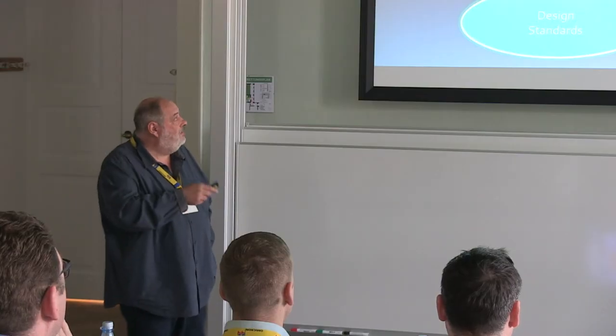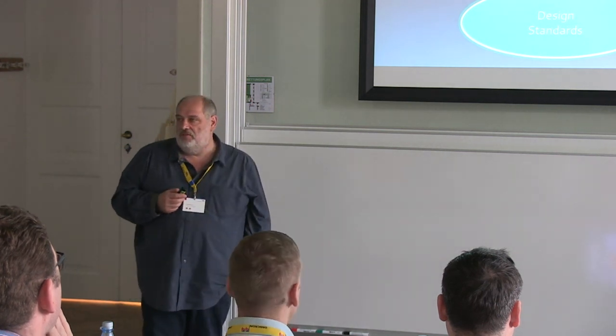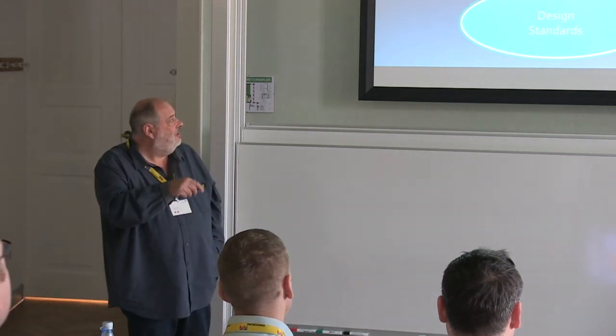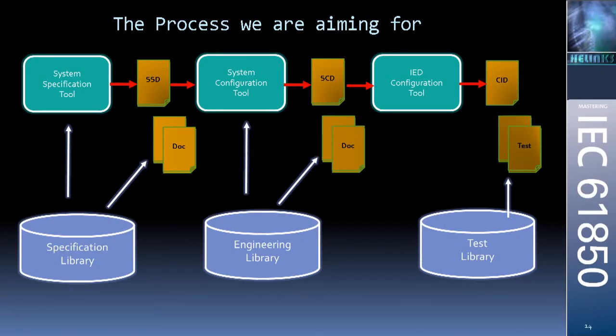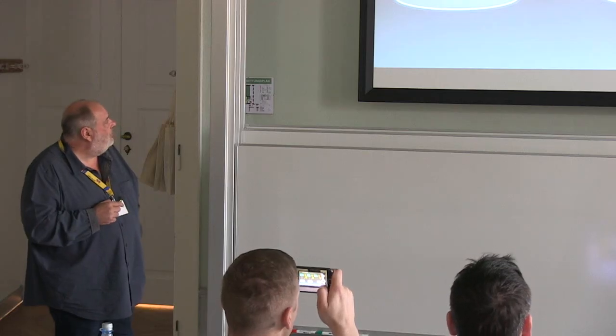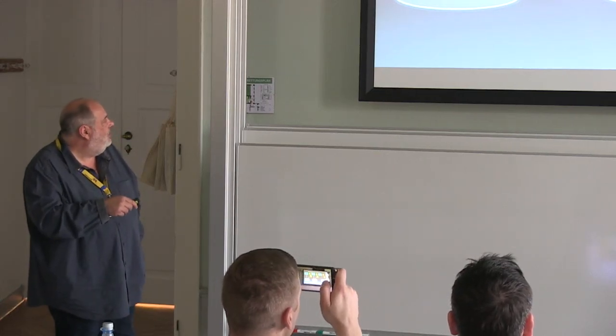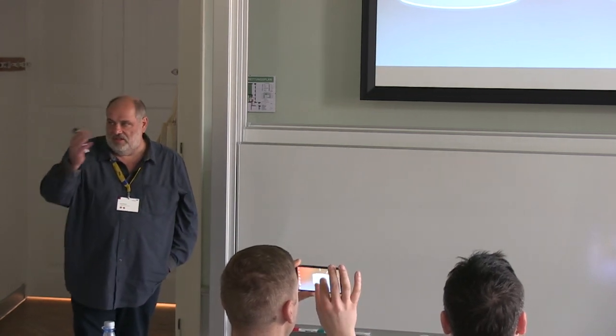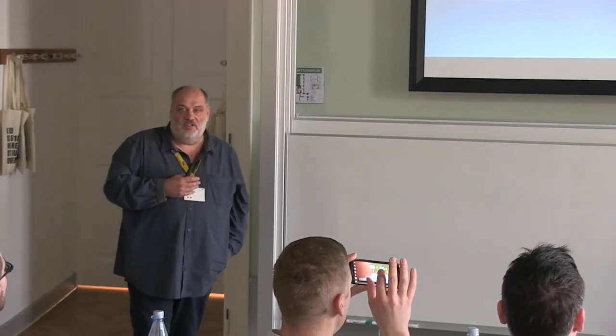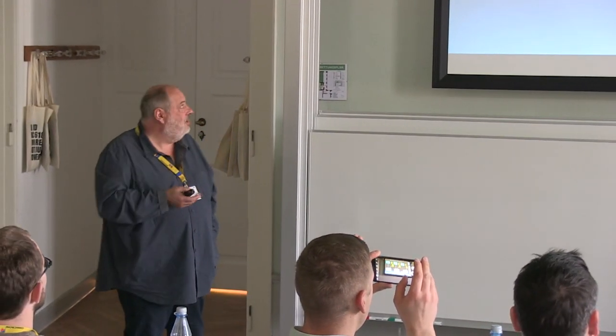And even with this, people are very often happy with 61850, just complaining that it is too complicated. What can we do now based on the functional modeling that I've presented? We can aim for such a process, even if there are some things to consider about what the granularity and details mean. So this is the ideal world. Somewhere we have a specification library which is completely independent of the relays. It just has logical nodes, also signals, functional decomposition of our system according to our understanding.